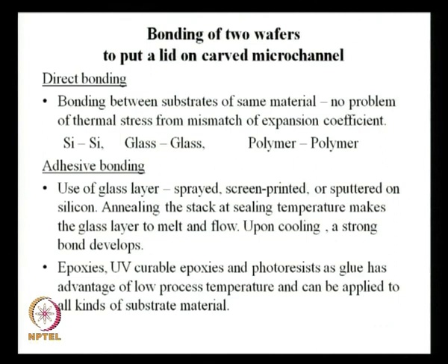Next is adhesive bonding. Here you can use a glass layer sprayed, screen printed or sputtered on silicon. Annealing the stack at sealing temperature makes the glass layer melt and flow. Upon cooling, a strong bond develops. So that means you have two layers, and in between you put some glass. How do you do that? A thin glass layer, either you